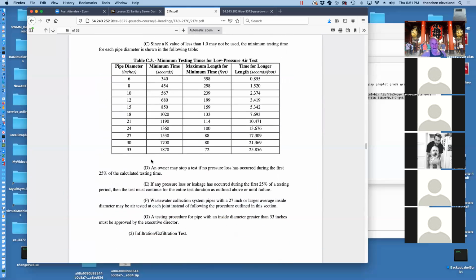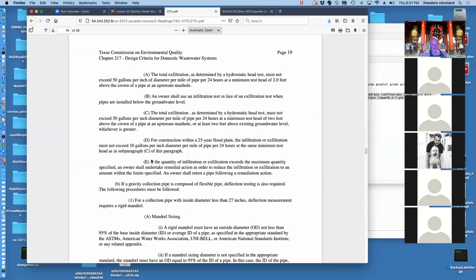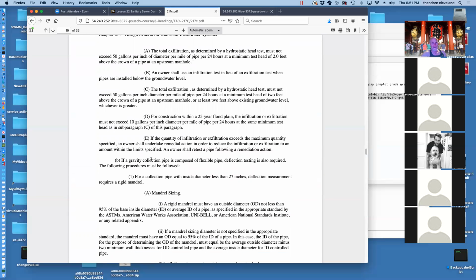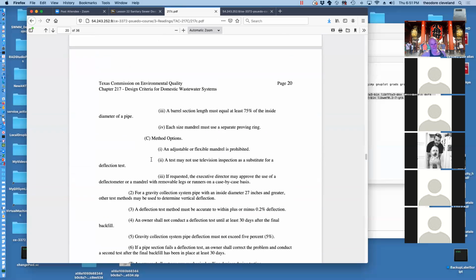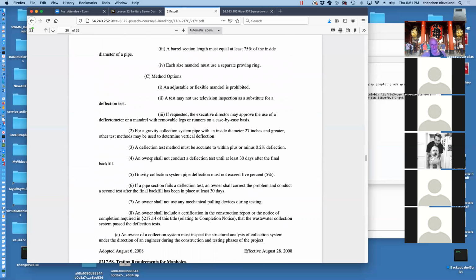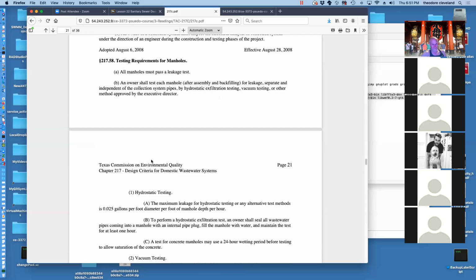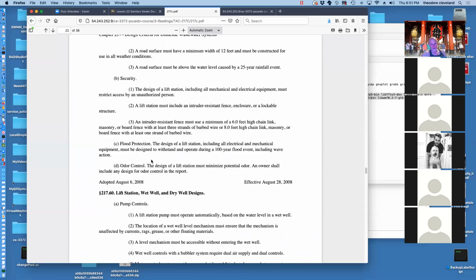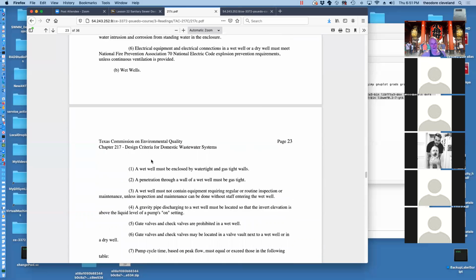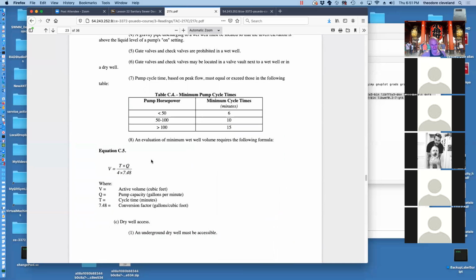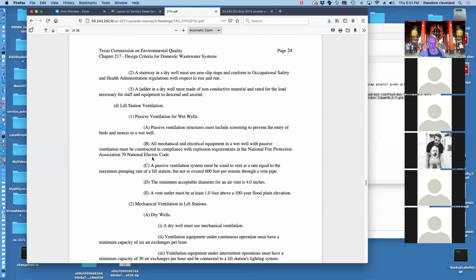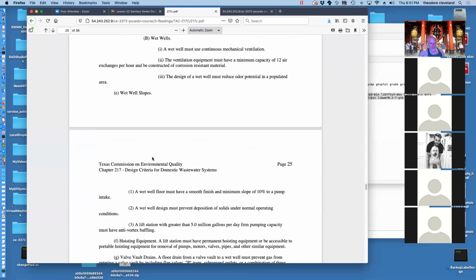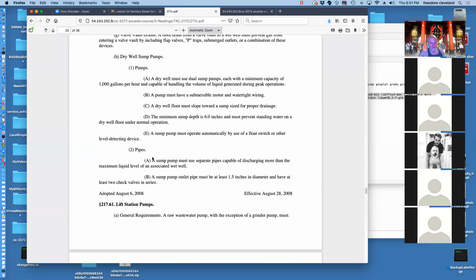And as we're moving down here, I think there is a section on burial depth. It's only if we stumble onto it, because I'm not going to be able to find it if I'm looking through it quickly. But I believe in Texas, the minimum burial depth is 3 feet. And less than that, there's insufficient soil to actually help distribute the surface pressures and protect the pipe itself.